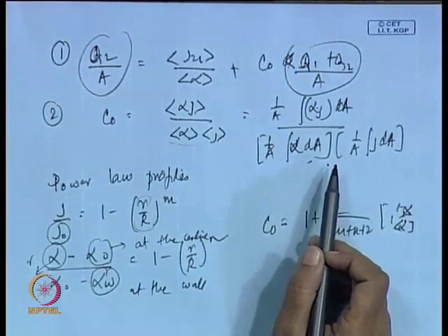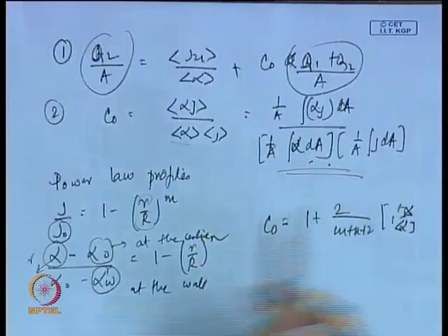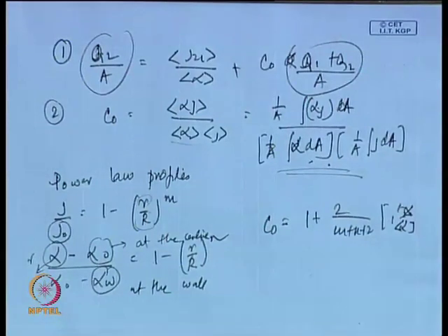There are two particular cases. One is when there is a heat flux and there is intense vaporization at the walls. Therefore, there is a larger vapor concentration at the walls as compared to the center. The other is when we are introducing air through, say, a porous wall. Then in the developing region, there is a greater concentration of air bubbles at the wall as compared to the center. For such cases, we cannot use the C0 values which I have written down in my PPT. They are mostly for fully developed flow cases or for those cases which have a convex sort of profile. So, for anything else, C0 has to be derived from the basic equation which I have written down.